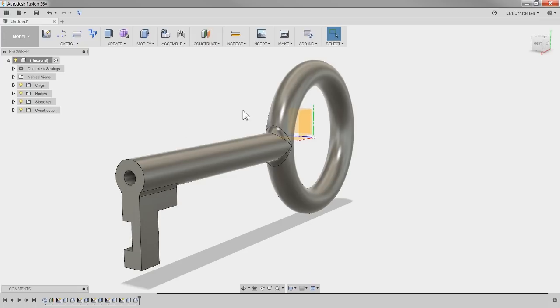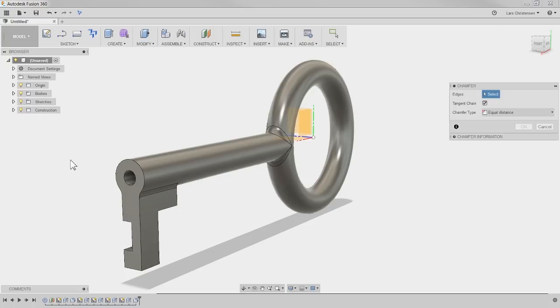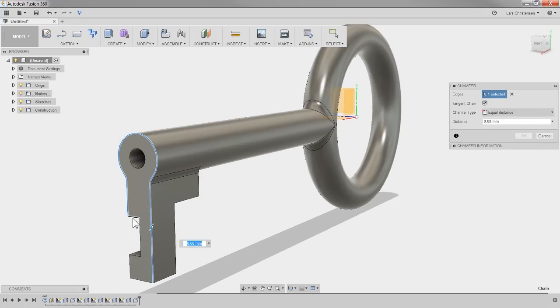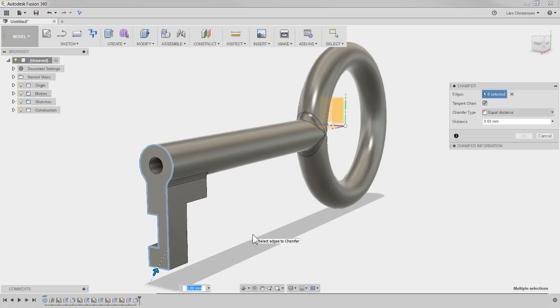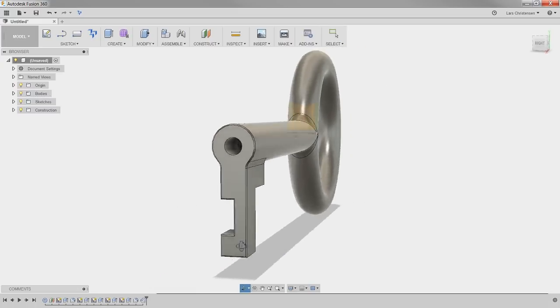And we can also put chamfers on it, so kind of like breaking the edges on it. So we can click the chamfer tool, and you will see that as I'm hovering over, it kind of like shows the edges here, and I can go in and select each of these different edges. Maybe give it just, I don't know, 0.5 maybe, 0.25.